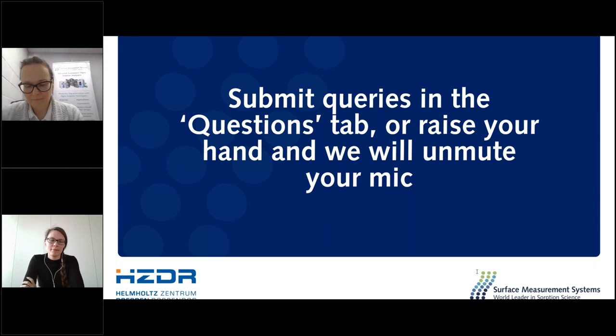Question here. They wonder, and forgive my lack of scientific parlance, if you have considered the Li loss during the flotation process. How can this issue be overcome? Yes, that's a good point, and it's actually something we've also analyzed. We saw that a lot of the lithium is in the solution afterwards. We have another PhD student, Eliza, whose PhD is on exactly this topic. She's analyzing the process water of flotation, using methods like ion exchange, so it's more the hydrometallurgical route to extract the lithium from the process water after flotation.